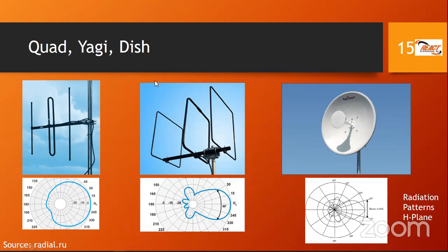All right, so forgive me, I neglected to label these, but when you get your slides, I will try to put the labels on. This first antenna on the left-hand side, we came across this already. This is a beam antenna. We have the driven element in the center here, and we have two other elements that we refer to as parasitic elements. So we have a reflector and a director. So the driven element in the center.